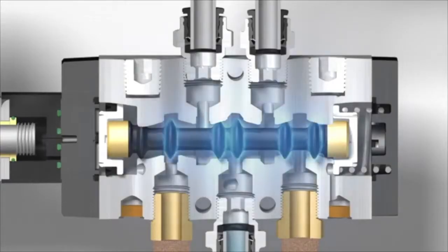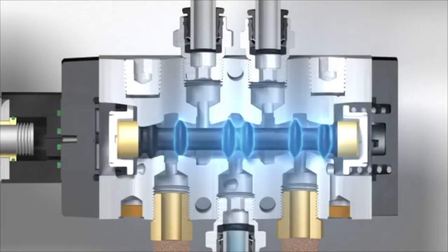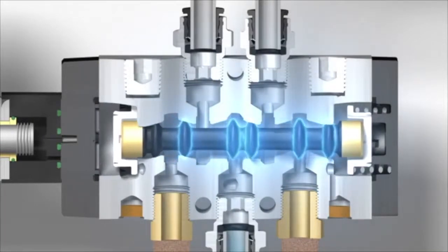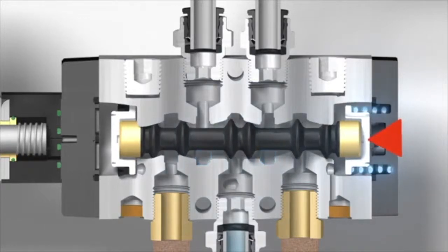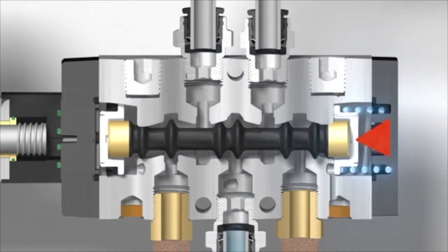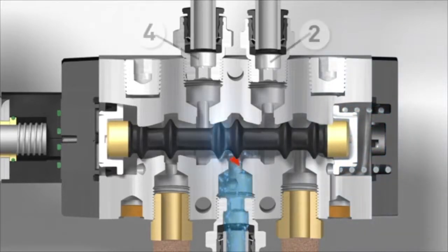The high spots on the spool, called lands, will block the air from proceeding down one path, while the lower sections on the spool, called grooves, will allow air to flow around them and proceed to one of the working ports. In this common type of valve, when the unit is not activated, the spool is forced to the left side of the valve by a spring. In this position, you can see that this land blocks air from going out the number 4 working port, and instead is forced to go out working port number 2, because the grooved lower section of the spool allows air to flow past it and out to the number 2 working port.